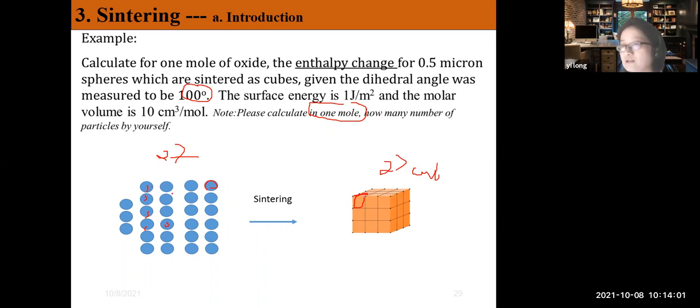First of all, let's calculate the total surface energy of this system. So total surface energy equals what? You should have learned this in many courses already. Tell me, what is the surface tension here? Gamma what? This is S, and the outside is vapor, right? Gamma SV, correct? You know that for each of these particles, because they're not contacting each other, they're only in contact with the vapor. So for each particle, you have gamma SV, right?